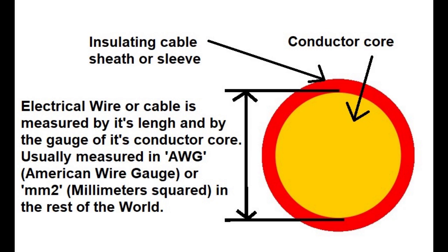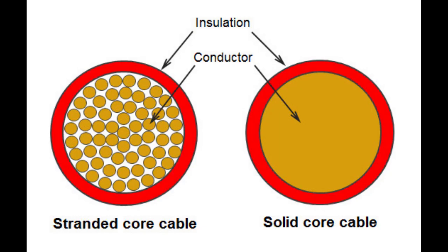The sheath itself may be specified as lightweight, flexible, or heavy duty. Thin wall is probably the most likely sheathing you're likely to use. You should figure out what wire sheath is best for whatever application you're using it for. I will make some suggestions later. Another thing that is seen in AC, probably more than DC wiring, is solid core conductor wiring. Rather than thin strands of wire, there is just one rather stiff rod of wire acting as the metal conductor with a sheath around it. You don't see this too often in DC wiring.